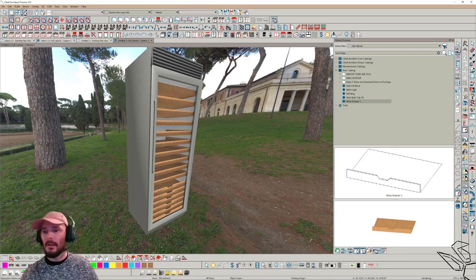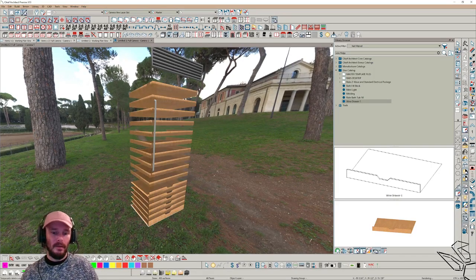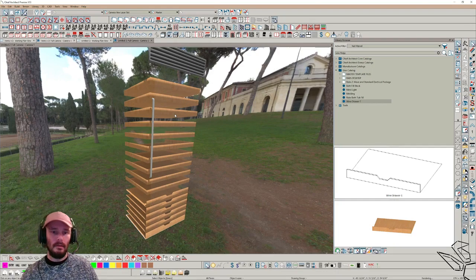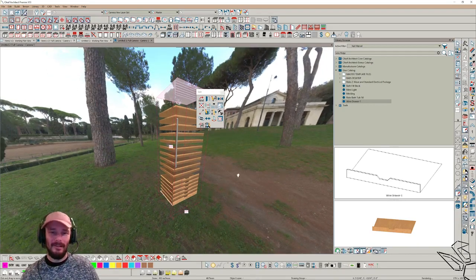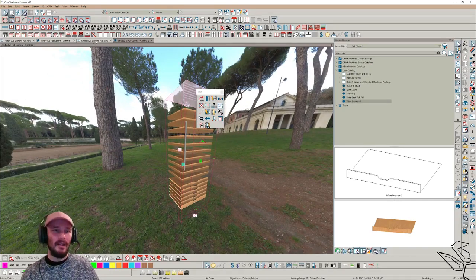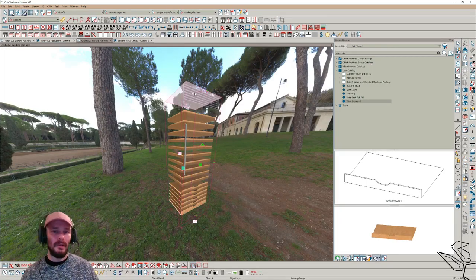So if I use my delete surface tool and I delete a bunch of items, and then I hit F5, which rebuilds 3D, what's going to happen? It's going to come back. Or it's not going to do what I said, and I'm wrong. But making a few edits, like jumping off of this view, coming back to it, will definitely bring this back into place.